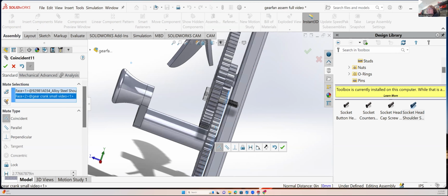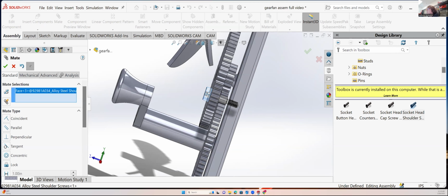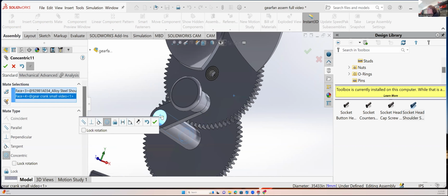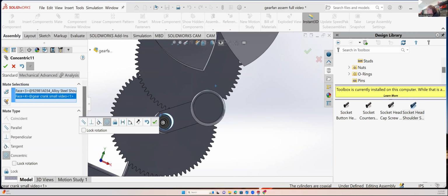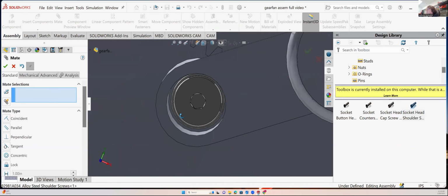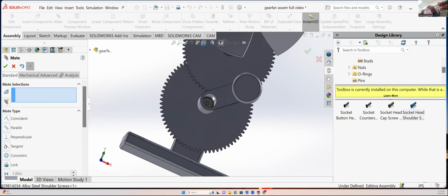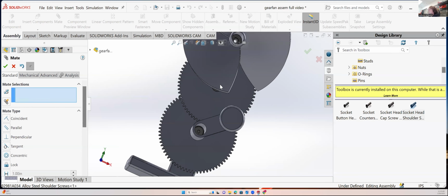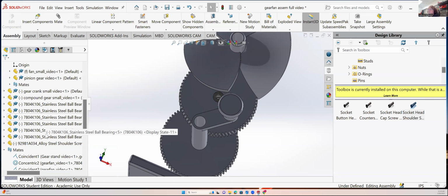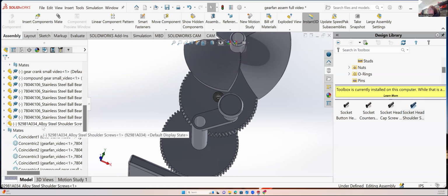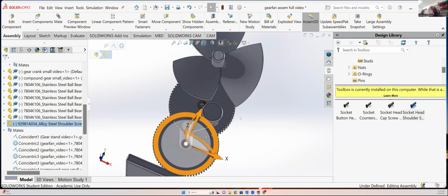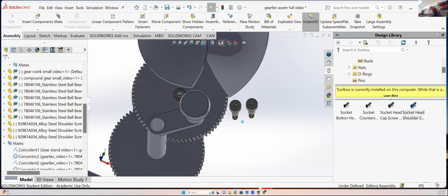So we're going to make that one coincident, yes. We're going to make that one concentric inside there. So let's see. Yep, we got that. And yep, we indeed have clearance around it, so we should be just fine there. Might even be able to make that inner diameter a little bit smaller if we really wanted to, but I'm going to say that's fine. So yep, let's copy that two more times. The shoulder bolt that is. Yep, copy two of those.